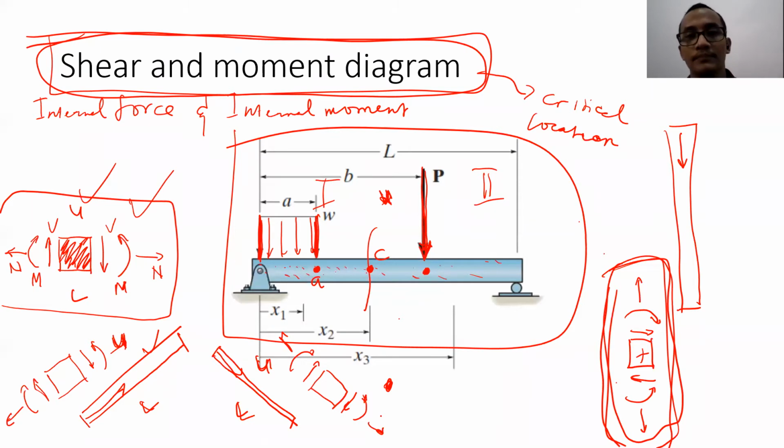So for vertical, it's safe to assume one of them. Yep, as long as you're consistent for the whole system. Correct. So it is better that you state from the beginning: this is the sign convention that I use in this particular structure.